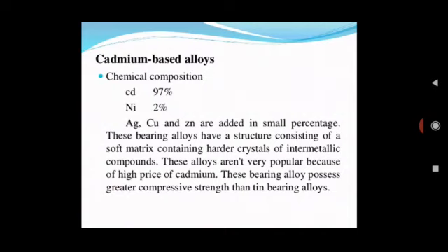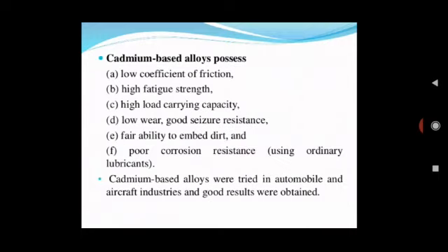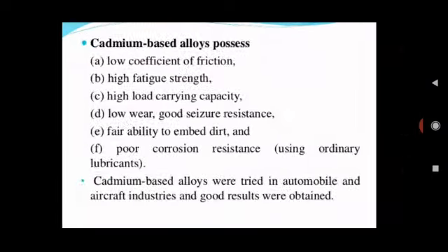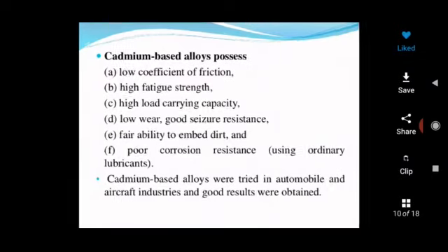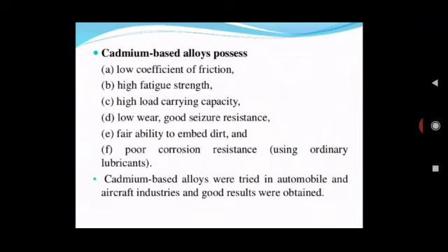It is more expensive, that is why it is not very common, and it is used in the automobile and aircraft industries. The properties of cadmium based alloy is that it has a low coefficient of friction. As we have seen earlier, low coefficient of friction is desirable, and the reason was wearing, degradation of material, and bearing life. Then we have high fatigue strength, load carrying capacity, shear resistance, good embeddability, but